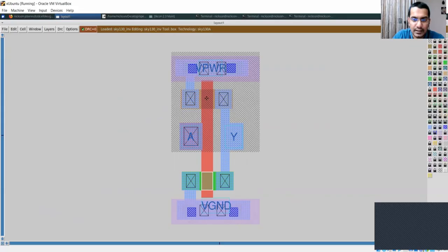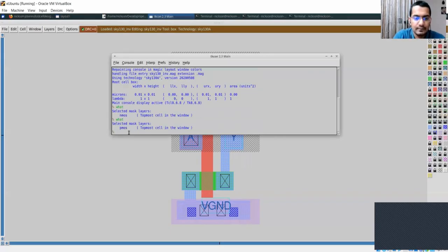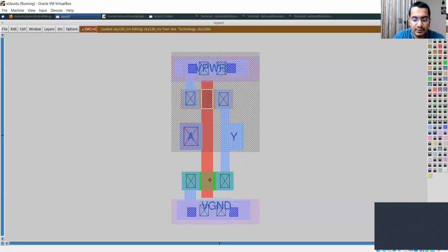So the steps remain the same. Now we are at mask 12. We'll spin this particular structure with photoresist and expose certain areas with the UV light. We will use mask 12 to protect the remaining layer. So this is mask 12. We are about to reach mask 16. So the next step is to remove the mask and etch off the SiO2 where we want to drill the contact holes. Now we decide to drill contact holes over here, and as well over here.